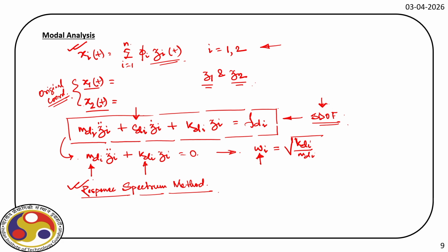You can actually add the floor model in your finite element analysis. But because we did not consider the floor slabs, we had to apply the respective loads on the beams, and for that we used the floor load given in STAAD.Pro to define the floor mass. We never actually evaluated the mass of the structure itself.